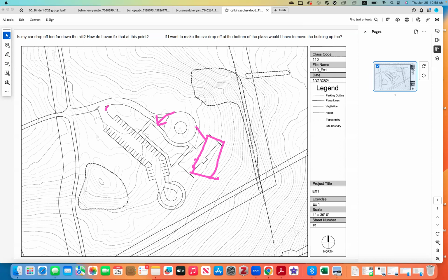Well, polishing your design by rounding the corners of the road, make it more a smoother road. And for here, you actually do not need to make a similar Y-shaped turnaround. You could basically just do a circle, okay? And we're getting to a pretty steep area, so try to reduce the size of the neck, right? You don't necessarily need such a long neck. Again, follow the grading class example, and then your plaza needs to connect to the front plaza.